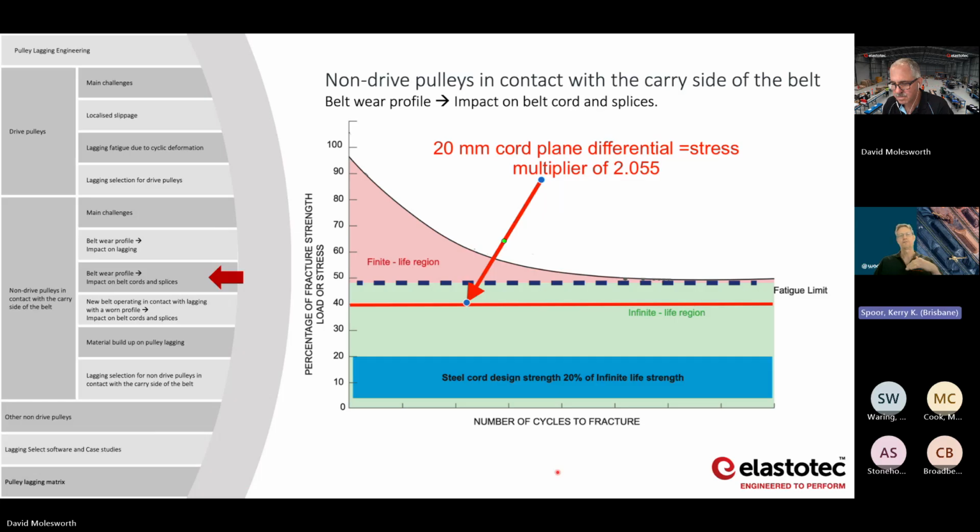The transition itself, as it approaches the drive pulley, generally leaves a W-shaped tension stress field. It's not homogeneous. As the belt approaches the pulley, you don't have this nice even tension spread across the belt. You have a W shape, a bit like what you were showing before from the chord misalignment. You get a double peak.